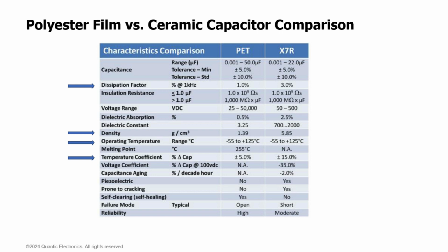MLP still exceeds in the areas of mechanical robustness, weight, ripple current handling capability, and overall efficiency. So far, MLPs are still the leader in those applications. It will be interesting to see over time what niches film and ceramic capacitors continue to fill as electrical technology and topologies continue to evolve.